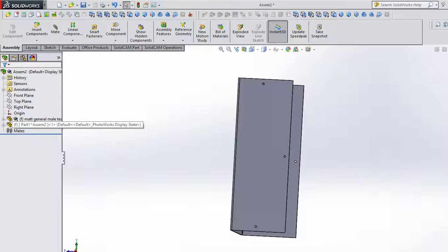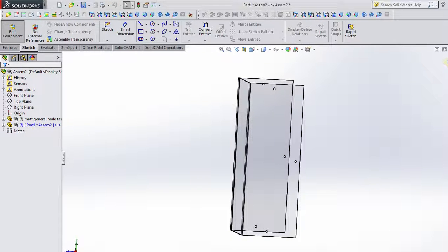So to get into this new part, you click it and then you need to hit Edit Part. You'll know that you're in good shape by seeing this little icon in the corner. What this means is, do you want to go back to the assembly? And the answer is no. We're working on this part. So you can see also here, this is turned blue. Now you know that you're editing, you're making this new part that has nothing, it's zero. There's nothing about it right now. But there it is. Okay, do you understand that part of it?